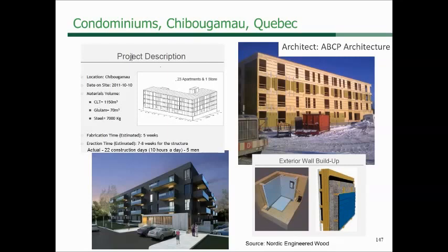One of the huge advantages that we just touched on barely is the actual erection process. Since a lot of this is fabricated off-site, they can quickly erect the structure. And this one, they thought it would take 7 to 8 weeks to erect, and it only took 22 construction days, working 5 men, 10 hours a day.